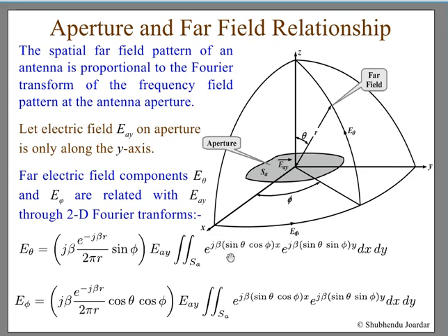the direction cosines. So sin theta cos phi: this r sin theta will be the projection here of r. Cos phi will bring it here, so the projection is along this one, this is x. And r sin theta sin phi will be this direction cosine projected in this direction. So you see that these are the direction cosines for this point. Then you can see the integral turns out to be a Fourier transform. And beta is the propagation constant or wave number. In some places in physics they call it wave number.